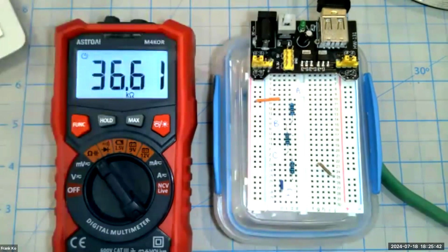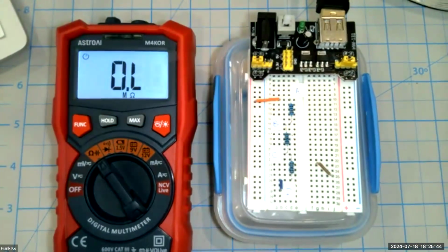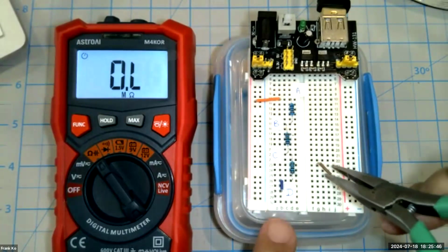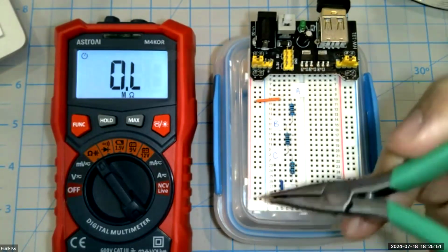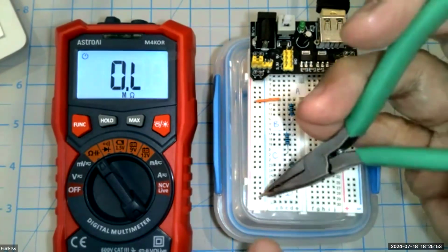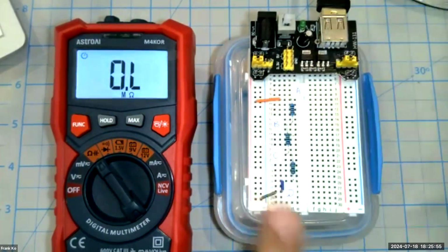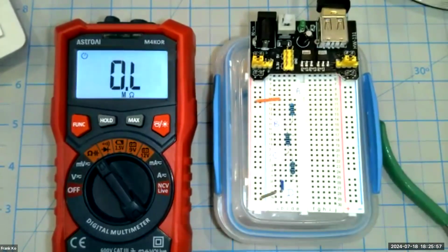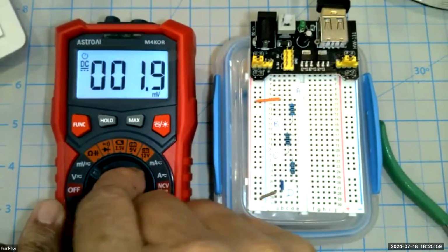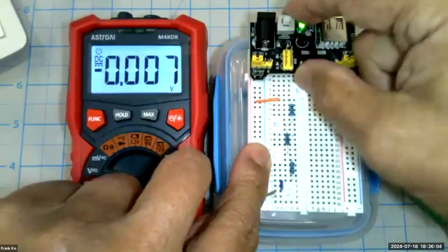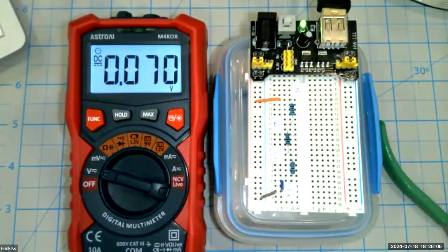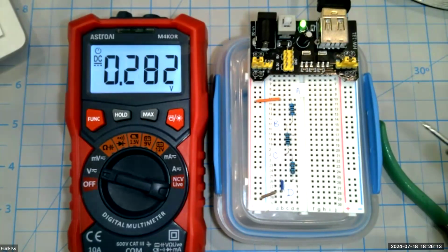Pretty sweet. Okay, next, after filling in your resistance measurements, we're now going to go to measuring our voltages. So I need to pop the jumper back, and we will go ahead and switch this to voltage mode and then now energize the circuit. And as we energize the circuit, we expected to see voltage across R1 as being something close to 1 volt.